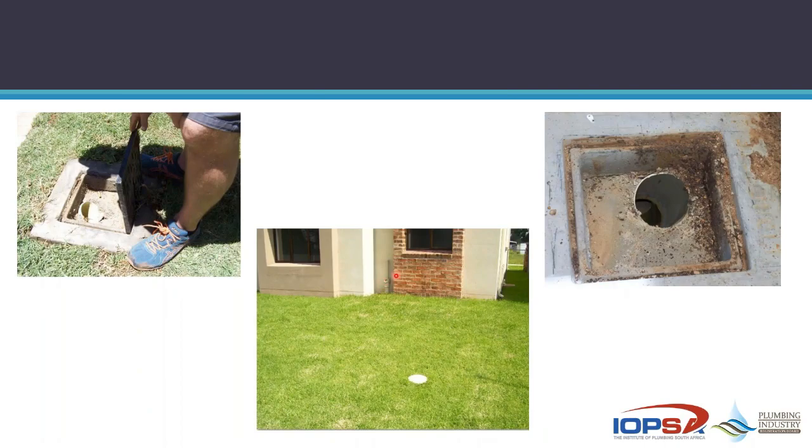Never mind the vent-on bend in the background there. You've got one plastic rodding eye here, you've got a fitting there, you've got a gully there, there's no access provided down that line there, there's nothing on the side here. So you get to site for a blocked drain and you look at this cover and you're not sure whether this thing is running towards you, away from you, towards that drain there. No access, no indication, one rodding eye on the whole premises.